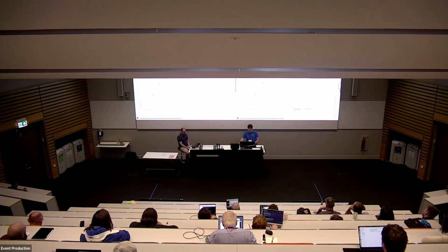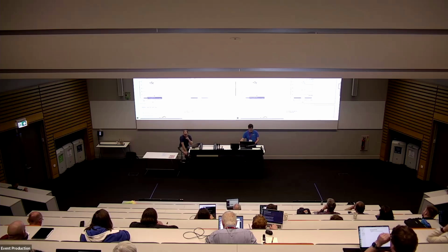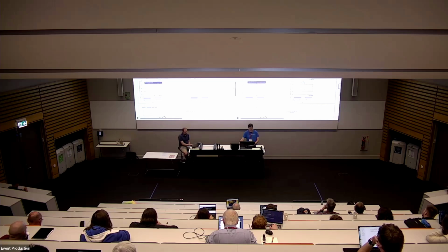Okay, so here's one we prepared earlier. This is an example from Stormberg where we actually had some overtopping events. There's no overtopping there in November up until 6 a.m. And then we start with the overtopping events and we get a metric of how frequently it is occurring. We do not get from this model a magnitude of the overtopping apart from the frequency. So that could mean a wave that is slightly coming over your seawall or quite dramatically.